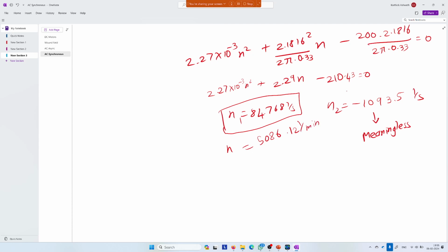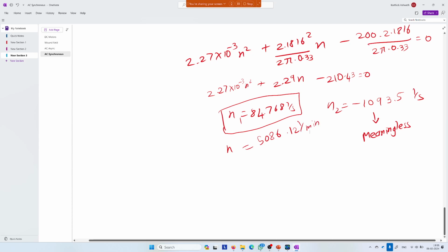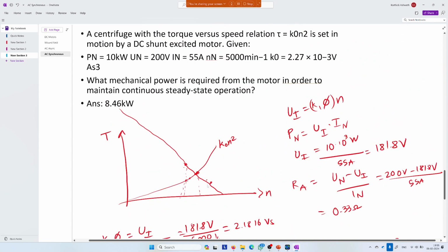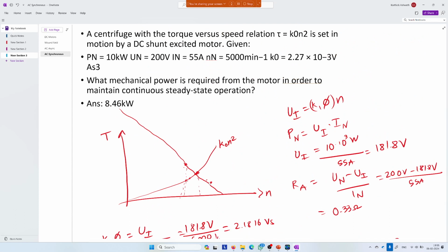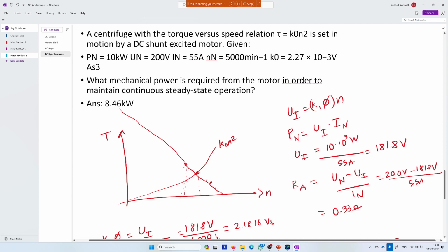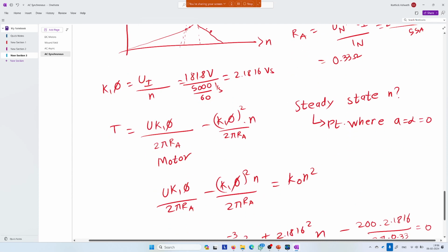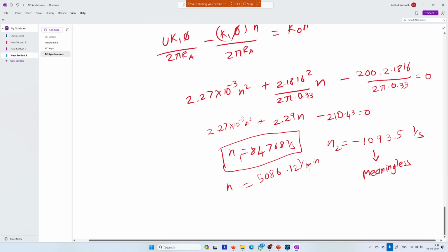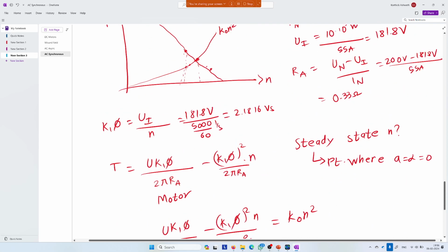Usually it's good if your design is having RPM higher than nominal, because then the slip, like, okay, there is no slip here, but just imagine it's somewhat like slip. So you can run it faster, it's fine, but running it slower means you're pulling more current which it's not rated for. So the operating point can be to the right of the nominal point in a good design, should be. So now we'll calculate torque.